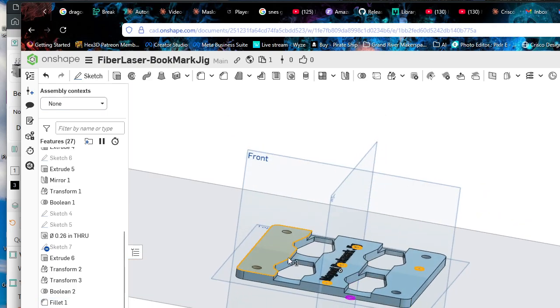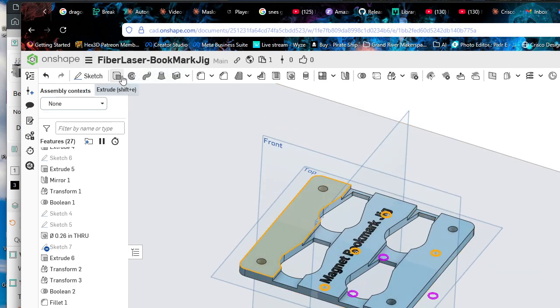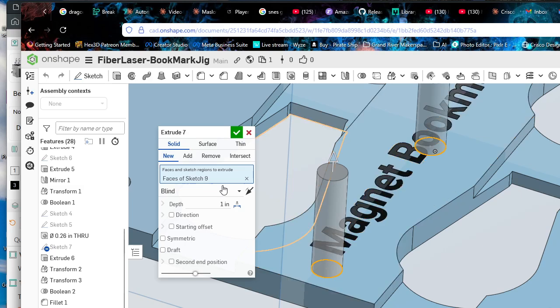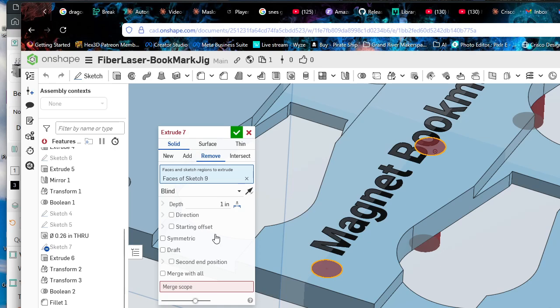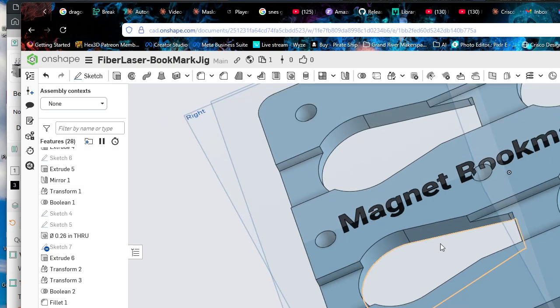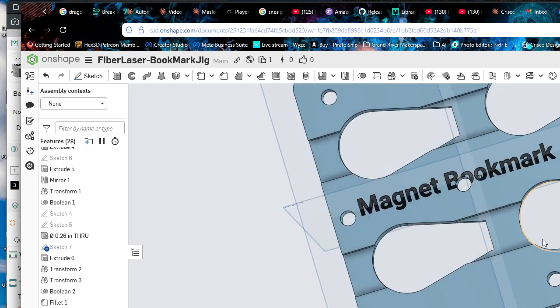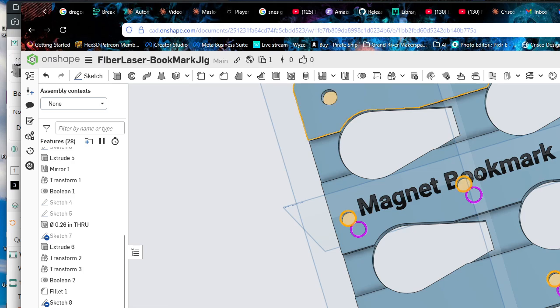So if I wanted to, I already have the holes spaced out on here, but if I wanted to make additional, I could add, basically I can reference other entities in an assembly in my part. And it creates like this, the logo next to it tells you, there's a little arrow next to it.